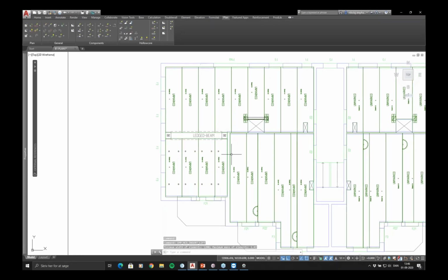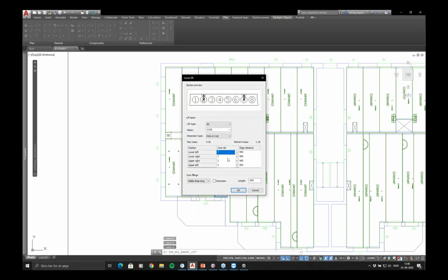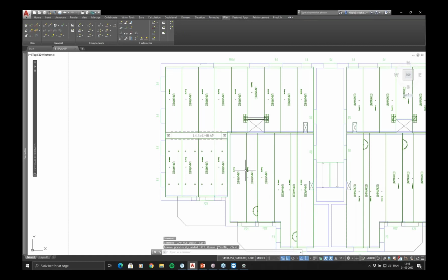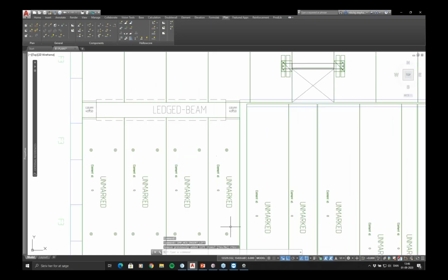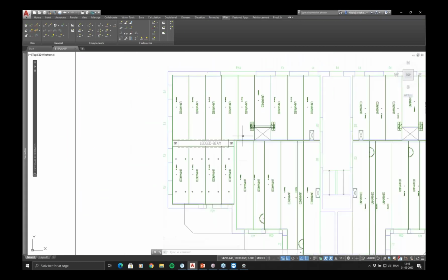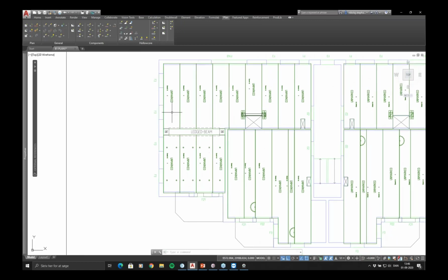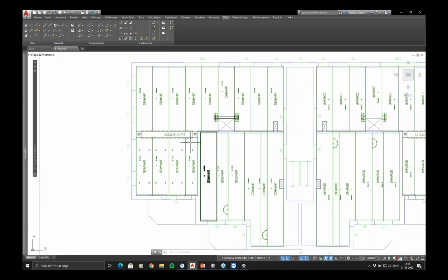As you can see, this one here didn't fit with the second row of lifters, but we can always go in and edit how we want the lifters to be placed. If we put this on automatic, there are also rules that can, for example, put them diagonally instead, so it'll lift properly and won't tip over when you lift it. And now we have placed the lifters here. So we have these straight cut elements here.